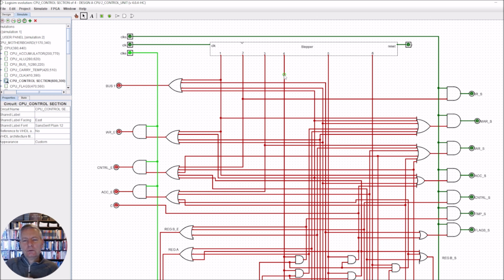So you can see there's a couple of options we've got in order to produce these complicated instructions. One thing we could do is fetch the instruction in, so that's 1, 2 and 3, and then do the execute, which could be 4, 5 and 6. But we could set it up so that in a complicated instruction, rather than going back to the fetch cycle, 1, 2 and 3, we don't bother with that. We go back round to 4, and then at 4 we can have another set and enable, set, enable, set, enable.